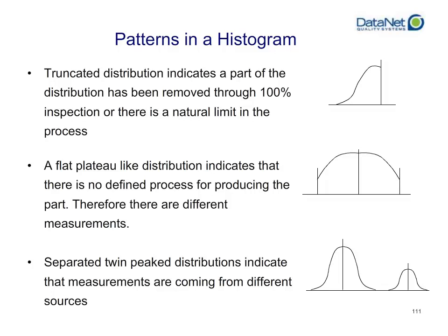The last pattern in the histogram that we see in this particular slide, separated with twin peaks: if you see two of these bell curve shape items, two of these natural distributions, that indicates you're measuring two distinct processes, things that should not be measured together. Maybe you are mixing the data from line A in your factory with the data from line B.